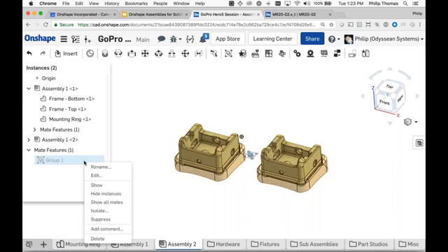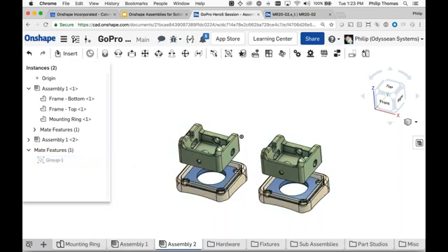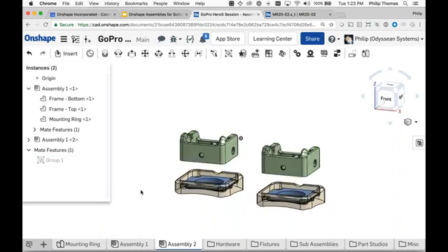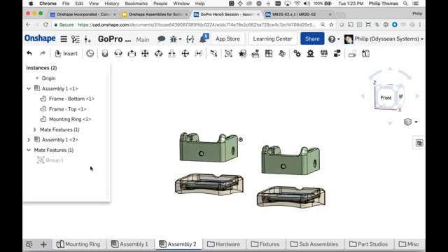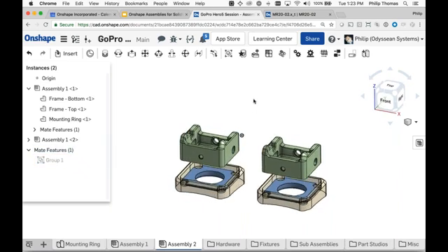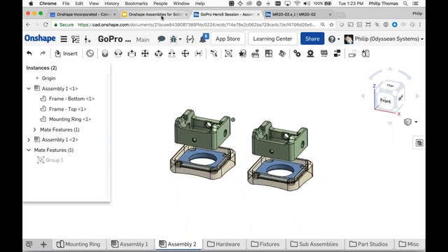If I want that update to propagate, I suppress this mate and then unsuppress it again. That allows that change to bubble up. Again, this is not a best practice. In fact, I just told you to not mate across sub-assemblies, or not group mate across sub-assemblies. And if you choose to do so, understand that a change to a sub-assembly won't propagate to the parent until you toggle the suppression state of that group mate. Tim is probably typing furiously at this point. Good.